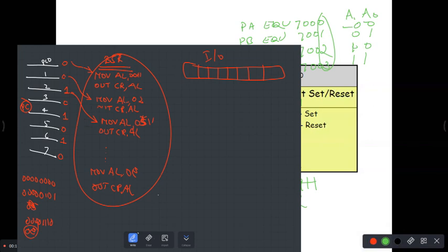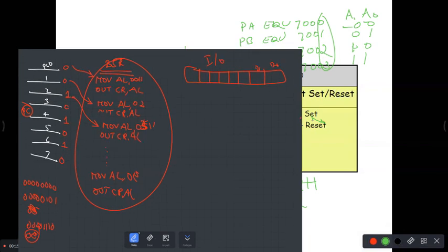Now in IO mode, first you have to configure the port. What is the port configuration? First you have to get a control word for the configuration of ports. So here port C we are using in the output mode, right? Okay. So which is the corresponding port C control word bit here? Come on, look at your mobile now. Which one is that? Tell me. D0. D0 is port C lower. Output, right? Output means 0.